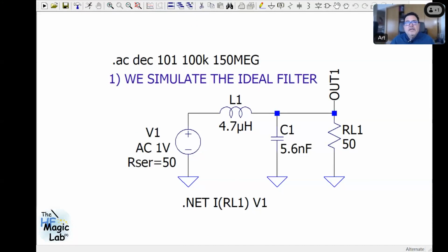source of the signal is the differential mode behavior of your power electronic circuit. What is the output impedance from 9 kilohertz to 30 megahertz, where you are measuring conducted emissions? It's unknown. Usually it's very difficult to specify what this impedance is at each frequency. Additionally, is it resistive, capacitive, inductive?